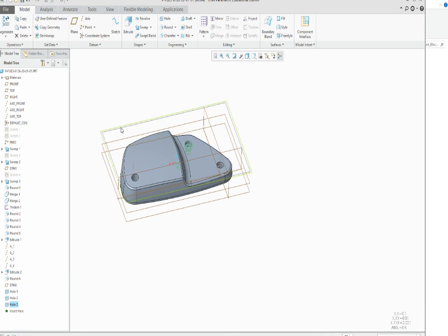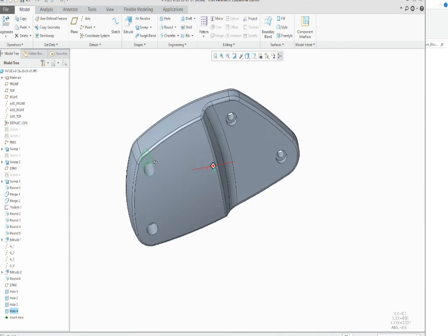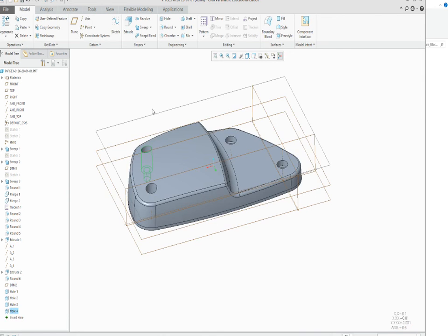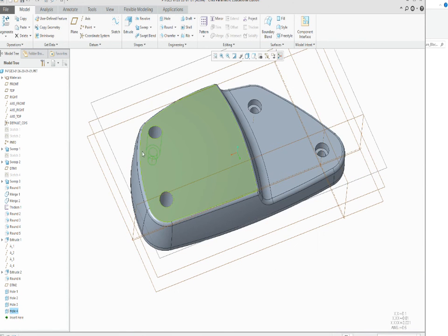And then the last one, we hit Control V. I'm selecting the plane first, Control V as in vector, and then I'm holding Shift and letting go on that axis right there. So right there we've got all the profiles, we've got the nice little cast on the design, and then we're going to hit save.